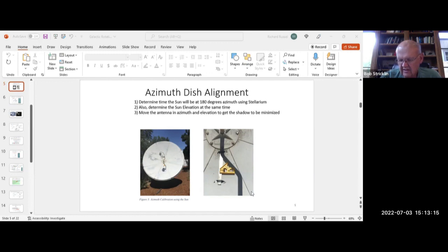I'm wondering if the 10% point could be a good reference point to decide that this is the beginning of the signal. Because if you start trying to pick that beginning time without some method, it's going to become some variation in your measurements, I'm thinking.